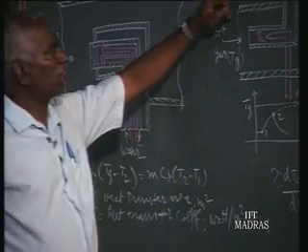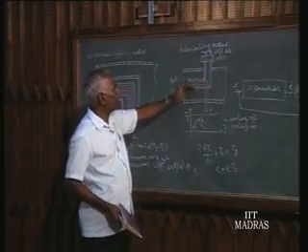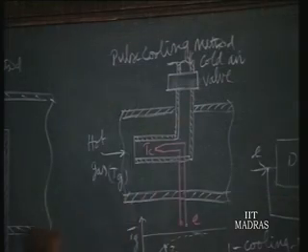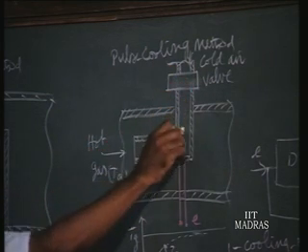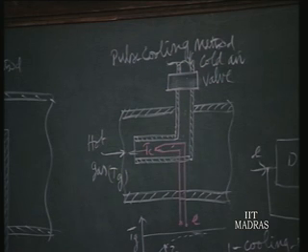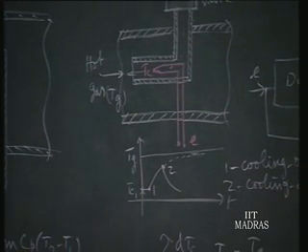We have got another method called the pulse cooling method. In this you have a pipeline carrying the cold air, and in the hot gas pipeline the thermocouple is situated. Normally the cold air is allowed through by the wall, and the cold air is at a higher pressure, so it flows from the inner pipe to the main pipe. So you will find the thermocouple junction is always at a smaller temperature, Tc1 for example. It is much less than the hot gas temperature.